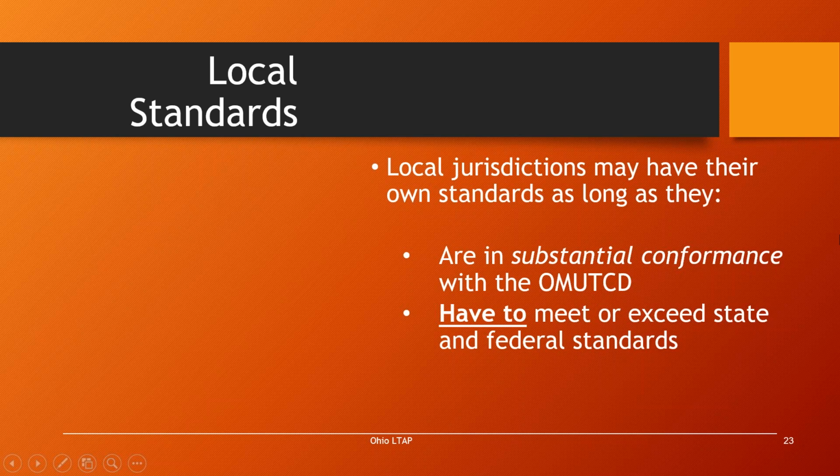So those are some instances where there are roadway conditions or designs that you're not going to find a typical application for. So you can use, and it's talked about in the manual, the other typical applications to help you figure out how to set up your work zones in those situations. But instead of making your employees, or their supervisors or your city engineer, try to design the situation from scratch every time they're out there, you should set up your own local standards. That way it makes it easier.